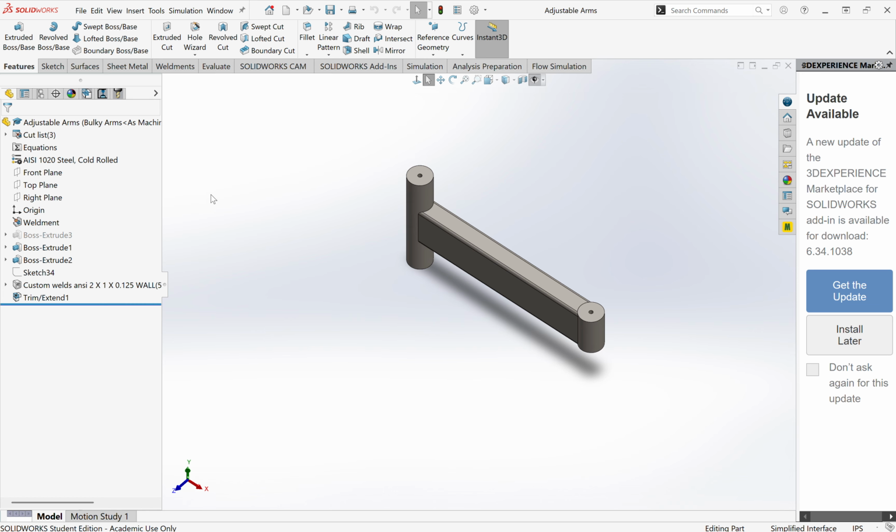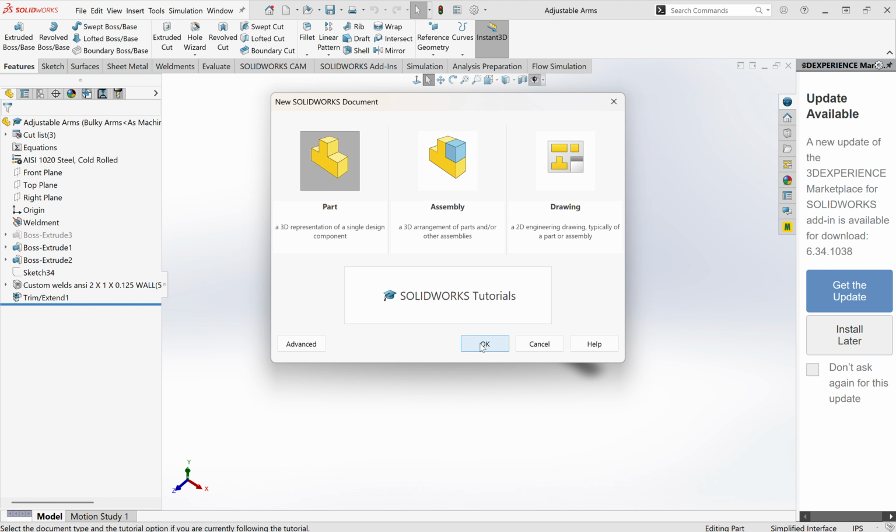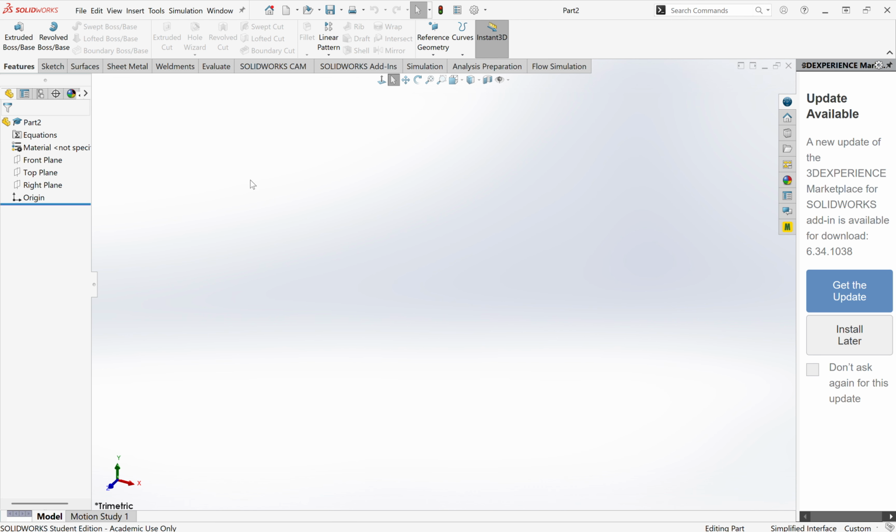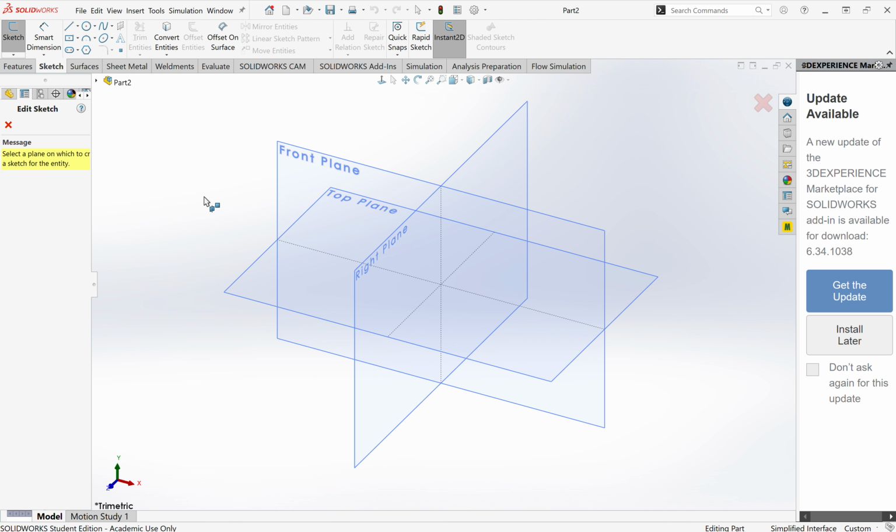The next thing is SolidWorks workflow. So the way to usually start a part, I'll go back up here, I'll press New, I will go to Part, and press OK. So I'll do a very basic example. Say we want to do a sketch, so you can go up here to Sketch, and then you're going to have all these three planes: front plane, top plane, and right plane. There's also the Cartesian coordinates over here, which is the Z, Y, and X, but I like to refer to them as the front plane, top plane, and right plane. So you can choose a plane from this point.